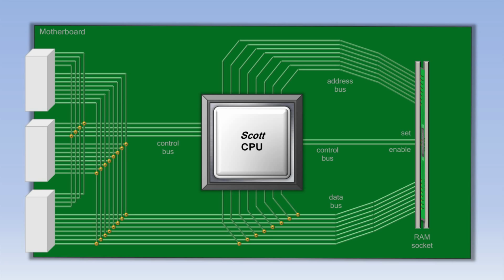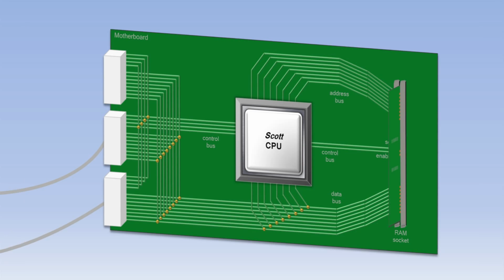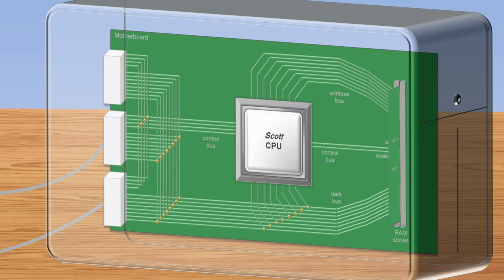Using the ports on the left, we can now plug in the cables that connect our monitor and our keyboard. Each of these ports has an address, and that port address is what the CPU uses with an in or an out instruction. That port address, by the way, is sent using the data bus, since the address bus in this computer is only used for RAM. So we'll zoom out to see how the motherboard fits inside the computer case.